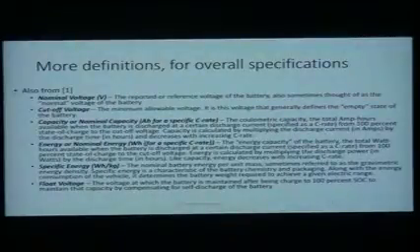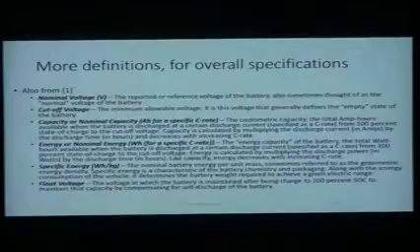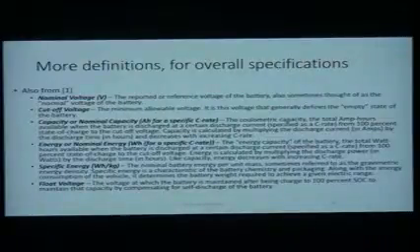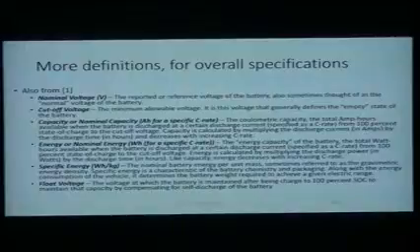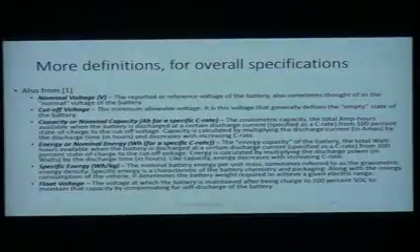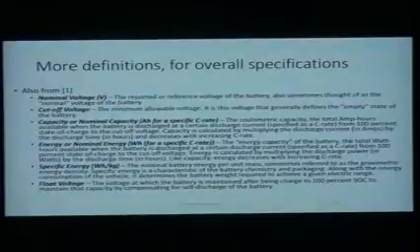So the last term here is the float voltage. The float voltage is the voltage that you maintain after being charged to 100%. It's the voltage that you need to keep on the device in order to offset self-discharge. So no battery is perfect. If you charge it up, it's going to slowly leak current. There's going to be reverse flow from diffusion and things like this on the inside of the battery, even if there's no connection on the outside. And so to counteract that, you would put a small extra voltage on your device. That's called the float voltage. Okay, and that's defined here.